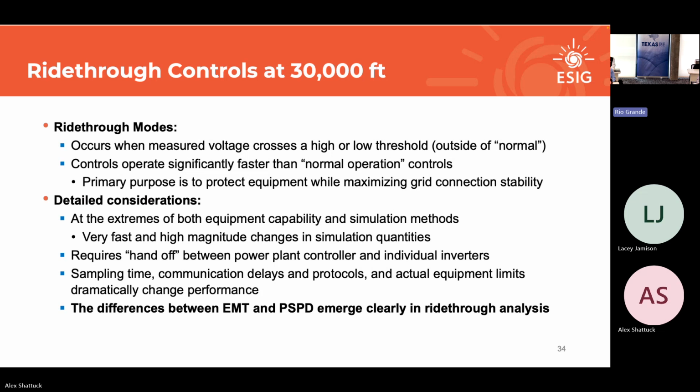So the big things for ride-through: you're at the extremes, really fast, really large fluctuations of frequency, voltage, whatever. You have that handoff between the inverters and the plant controllers, which can get complex depending on how many different things you have controlling the plant and whatever communication is set up. And the big thing, and really the EMT-specific thing, because even the best PSPD models don't have all of them, is sampling times. So how long does the equipment actually take to read a sample?